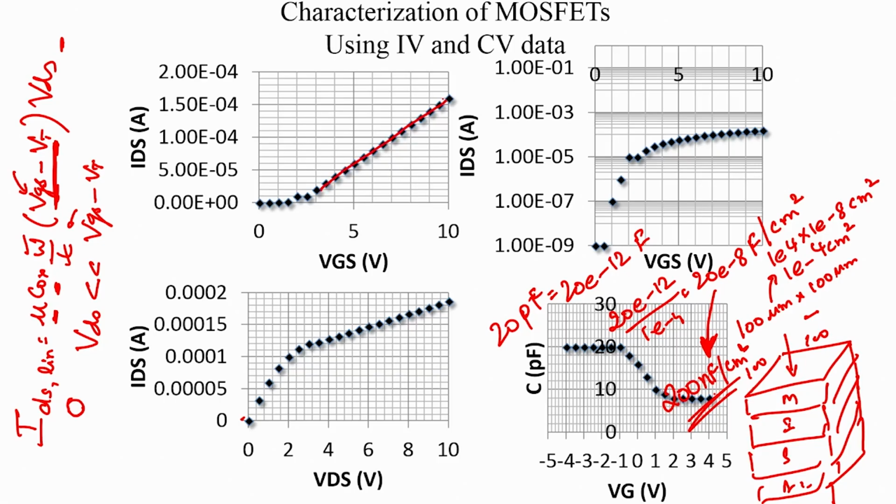So what is the slope here? So let us say this point here is about 1.5 e minus 4, that is the current, at 10 volts, and we will go a long way because these are quite linear characteristics, and let us say this was all plotted at VDS is equal to 1 volt. So over here we have a VGS of 5, here we have a VGS of 10, and here the current is about 5 e minus 5, okay, or let us say 0.5 e minus 4.